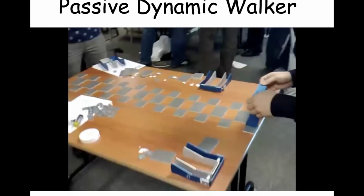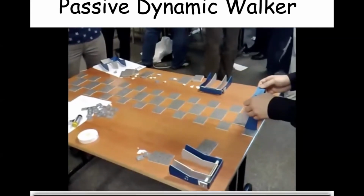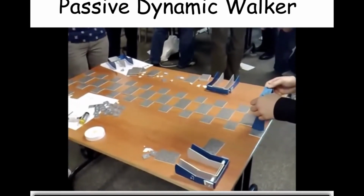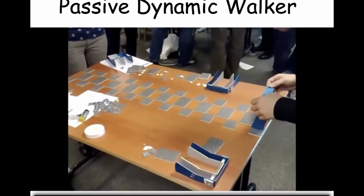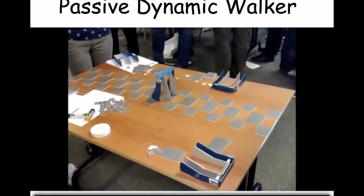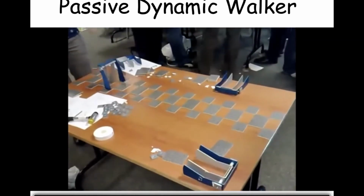So what we're going to do is simulate a Legate system, which is essentially two links. You can think of it as a double pendulum, but it turns out that the double pendulum, when you put it in the right configuration, can actually walk. And so here's how you can build a walker based on a double pendulum. If you get the initial conditions just right, then this walker walks downhill.